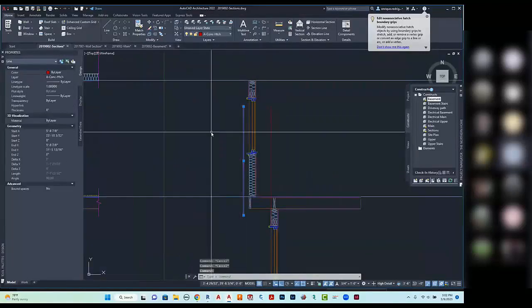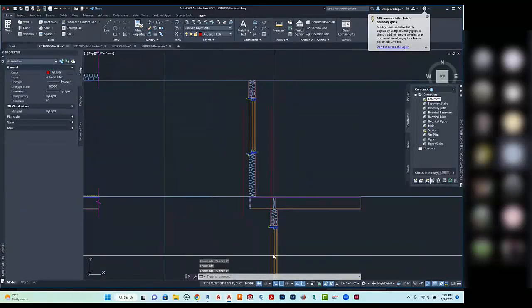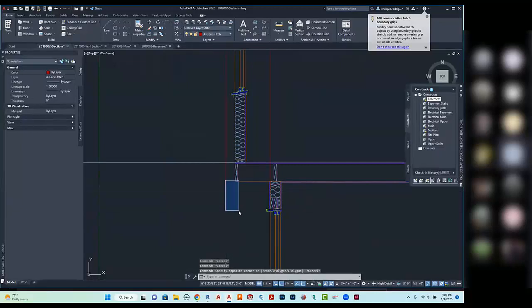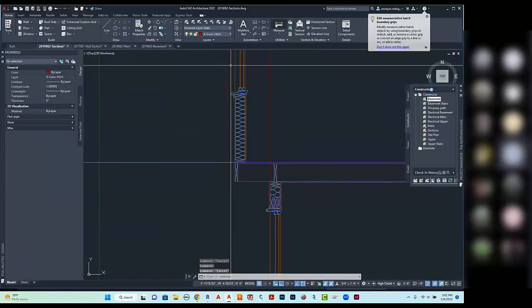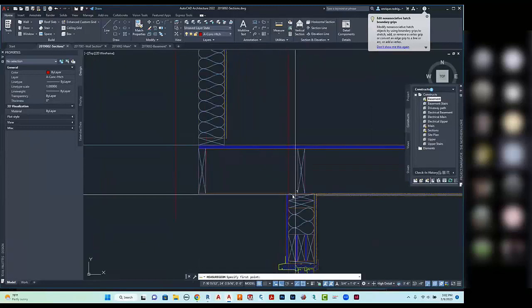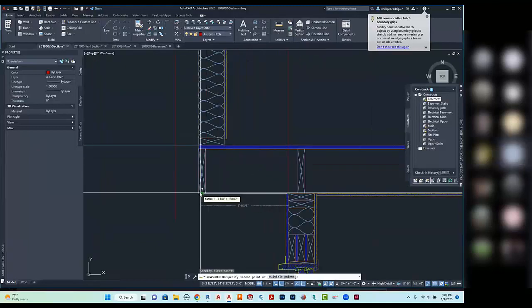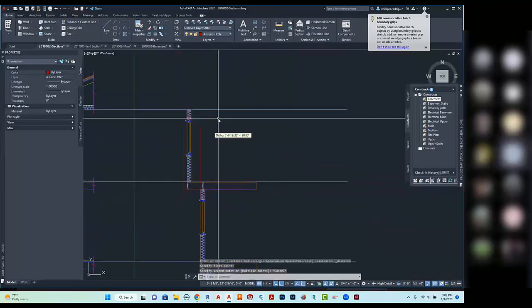I'm going to go ahead and double check, make sure that this line in here is the 2 feet over. I may have to pull all this over. So let's check. You see something that may cause a question. Let's go ahead and measure our distance. From here to here should be 2 feet. That's 1'7". So there's something off. That is our actual 2 feet in there.